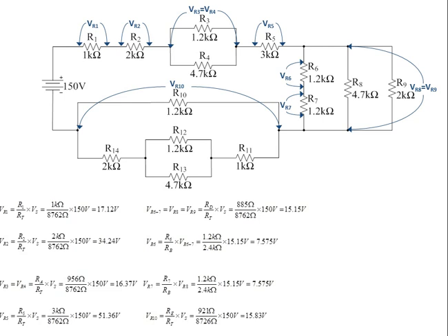So this is also going to be the voltage across the bottom branch of this parallel section, and we're going to need to divide that down further to get the voltage across R14, R12 and R13 and R11. So to get the voltage across R11, we put R11 over the total resistance of this bottom branch of this parallel section, which we worked out earlier to be RC, and multiply it by the voltage across this bottom branch, and we get that VR11 equals 4 volts.